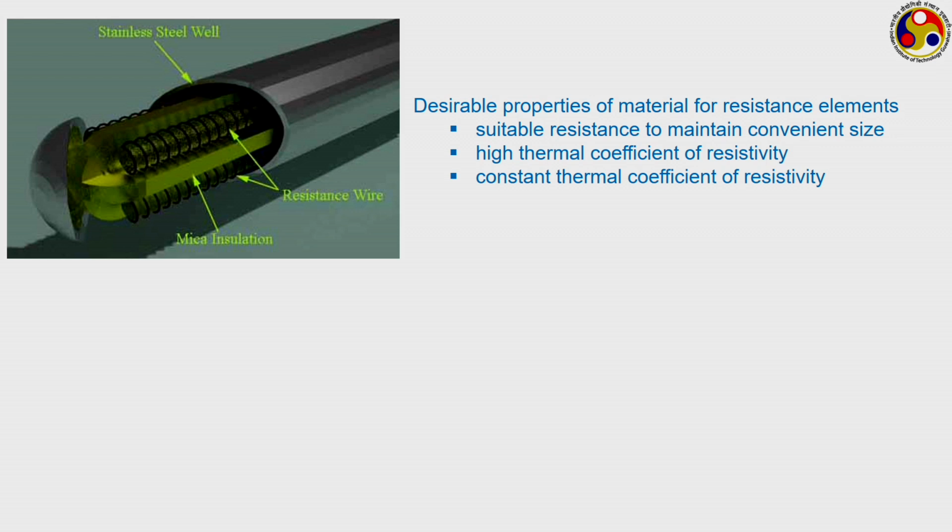However, that was not the case with nickel and copper. If the thermal coefficient of resistance is not constant, then we are not going to get a linear scale. Only if it is constant can you get a linear scale, which is possible for platinum over a smaller temperature range. For other materials, or for larger temperature changes, we generally get a non-linear scale.